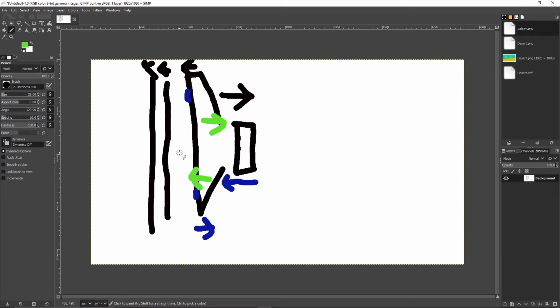Now, when we talk about the torque converter and the automatic transmission, there is no mechanical connection. So you cannot leave your automatic transmission in drive on a hill. It will roll. This also is why if you have a manual car, you can pop the clutch to jump start it. Let's pretend your battery died. We can go push your car, you put it in first, drop the clutch. It will make the engine rotate. It will jump start the car. You can't do that in an automatic because it doesn't have this mechanical connection here.